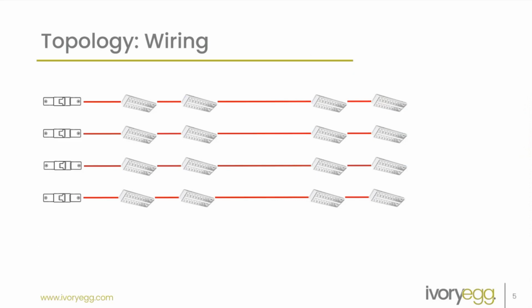So what I've done here is I've kind of changed this slide from the last time we did it, and I've included this new slide to give people a real representation of typically how Dali networks happen. So what I've got here, you can see on the left-hand side is circuit breakers. Those circuit breakers are fed from different phases. They can be fed from different parts of the building. And those circuit breakers feed active, neutral, and earth through to light fittings. Okay, so that way the light fittings are conveniently arranged depending on the circuitry, the amount of wiring, how many boards, and stuff like that. It's got no influence on the Dali.